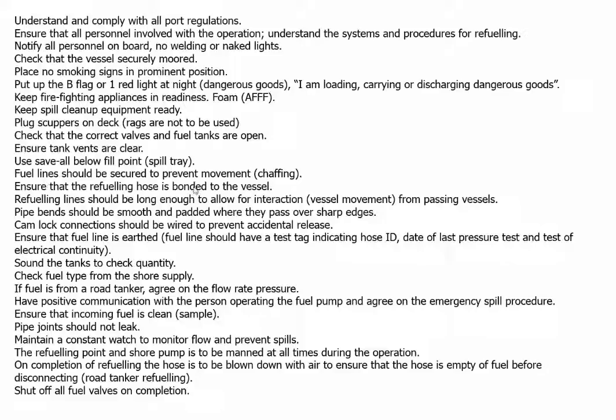Ensure the refueling hose is bonded to the vessel. We'll talk about that. Refueling lines should be long enough to allow for movement from the vessel or from passing vessels. Smooth bends, no sharp edges. Cam lock connections wired. Fuel line is earthed. We'll talk a bit more about that.